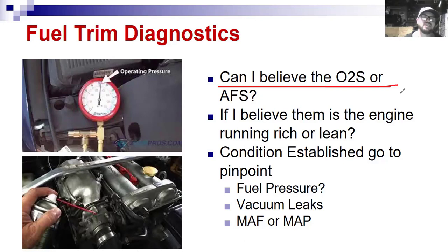And now it makes all the other cylinders that aren't misfiring run too rich. So again, this isn't foolproof. We have to definitely use our smarts to determine, is this lying to me or not? So I'm always looking for things like exhaust leaks and misfires. And then what I'll do is what we're showing in the picture here.